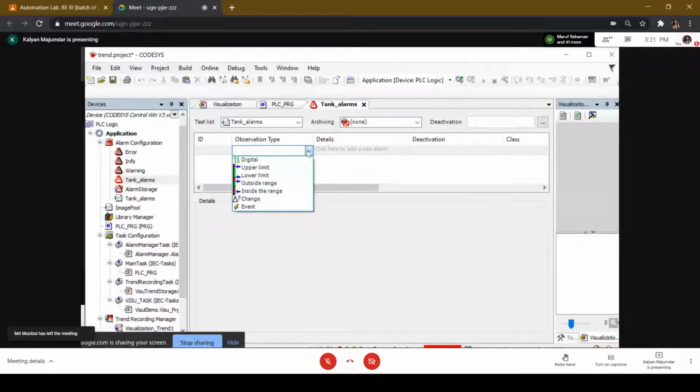The sump level is a Boolean variable with only two states: sump level sufficient is the normal state, and sump level insufficient, meaning you don't have enough water in the lower tank, is the abnormal state that generates an alarm. So one is the digital alarm, fine.